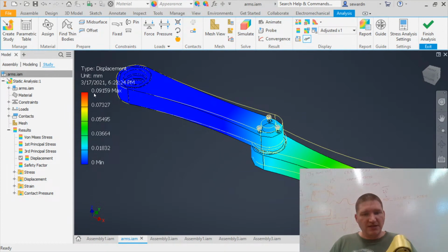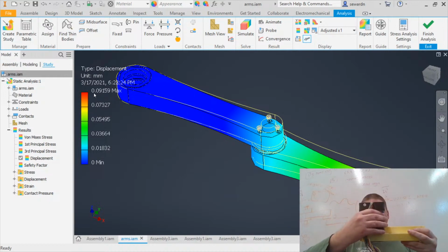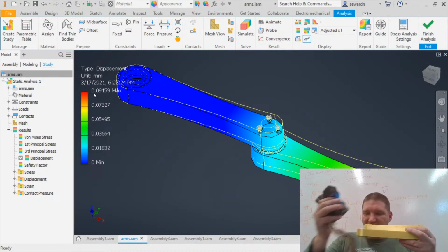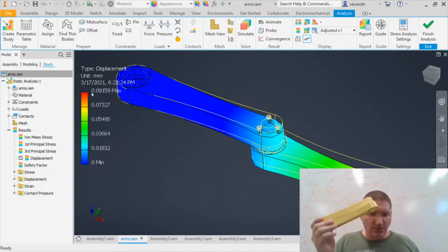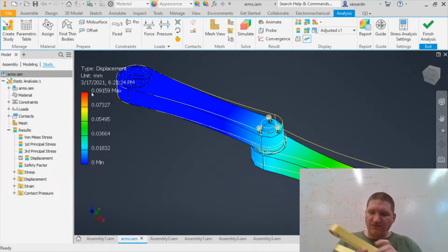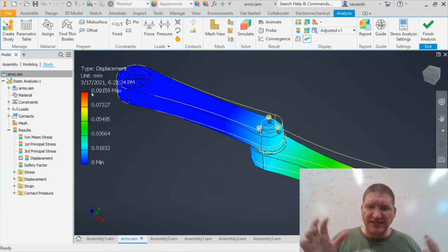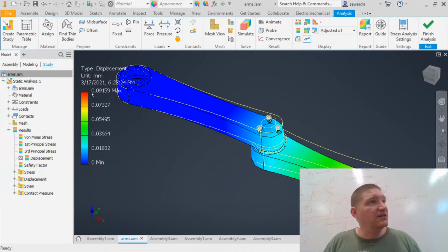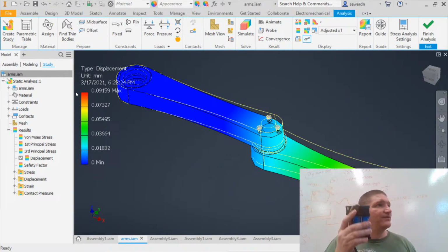But what I did do is I took this and I clamped one into the table, and then I set this on the other side, and I measured the deflection roughly, very, very roughly. And I got, with this arm has like 4 perimeters and 60% infill, so it's pretty hefty. I got about a little less, like probably half to 1 millimeter of deflection, and this is a crap ton more weight than I'm going to actually put on the end. So I'm feeling pretty confident.